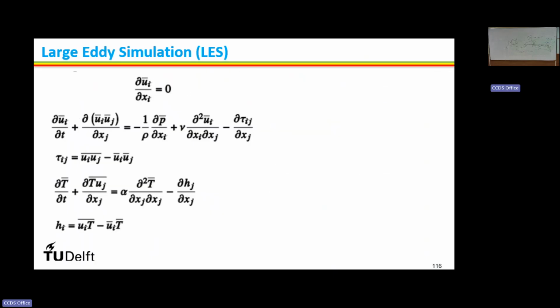Okay. Now this is my Navier-Stokes equation, right? If I do the averaging, what will happen? This is a linear continuity equation, it is linear, so the averaged fluctuation goes to 0. From this nonlinear term, this gives rise to another term, right? In terms of Reynolds averaging, we call it Reynolds stress, right? Here what do we call it? In LES, it is called the subgrid scale stress.